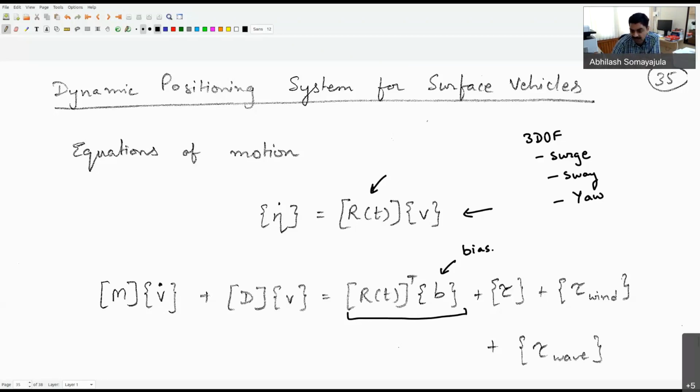Because we will have an integral component in our controller to compensate for these dynamic effects, for now we don't care so much about accurately modeling them, because we are not doing a feedforward control system here, but rather compensating for them using the integrator. So we are not so worried about the dynamics being captured properly.